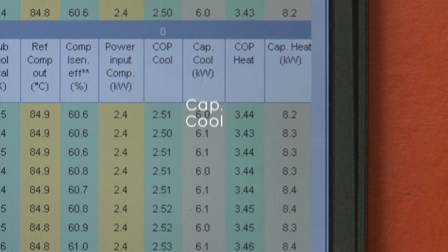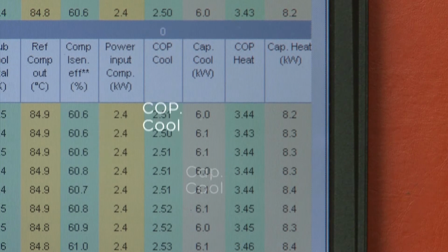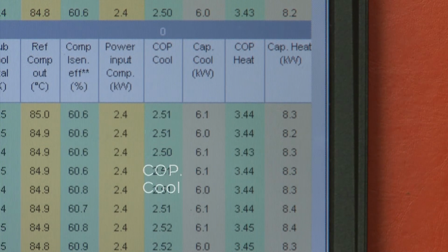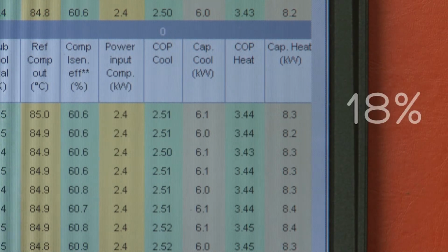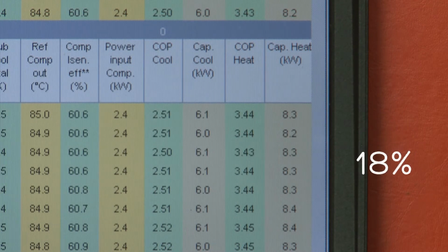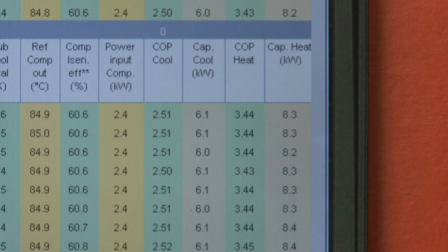But also what we've looked at is if you don't maintain a refrigeration plant and the system operates on a low charge, how that affects the running conditions. And we've seen the cooling capacity come down, but probably more important, we've seen the COP reduced by 18%. So that's going to cost you extra in electrical running costs, but also the machine might operate outside its operating conditions. So our work here is nearly done.